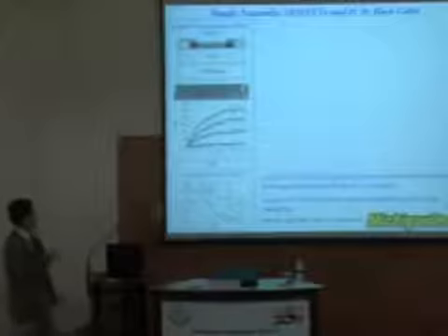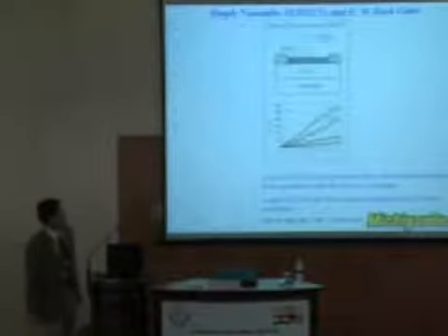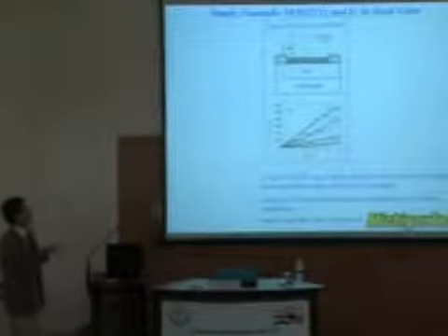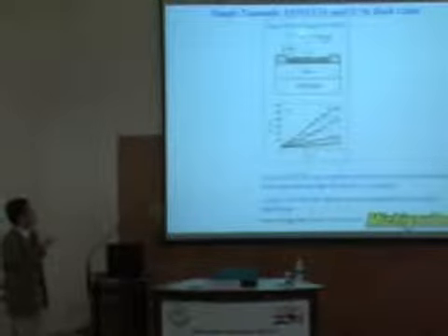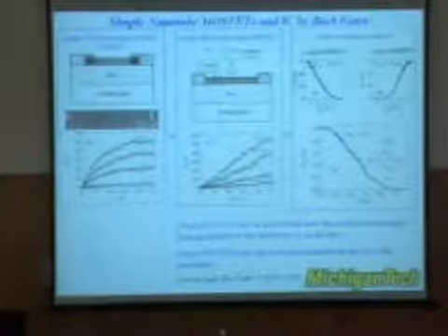And from here, this paper already defined how to form the so-called inverter, a logic circuit, based on the p-type nanotubes. Or alternatively, you can dope by evaporating some sodium vapor on the nanotubes. You can convert the p-type to n-type nanotubes. And in this case, if you combine both the p and n types together, you can basically form the complementary logic circuit as shown here.